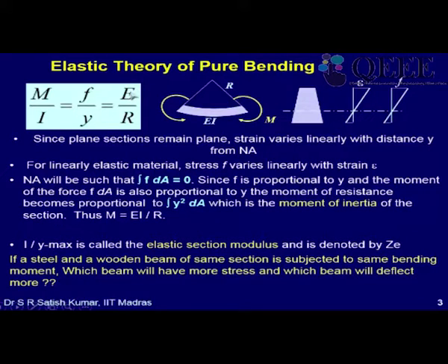The second question is, now if Fy, that is the yield strength, is increased, obviously the moment capacity will go up. So if you have a higher strength steel, my moment capacity, or moment of resistance as we call it, is Ze, that is I by y, into Fy, right? So if I increase Fy, let's say for mild steel Fy will be about 250 MPa, whereas for high strength steel it could be 350 or even up to 550 MPa and all. So if I increase Fy, I'll get a larger moment of resistance.